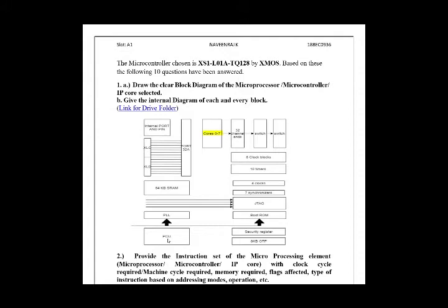Suppose there's some oscillator frequency, and we have some tile frequency. Based on this, the PLL ratio is set, and there are some PLL settings too: OD, F, and R. That's out of scope, but the OD, F, and R values can be modified by writing to a digital node PLL configuration register. There's something called the PLL configuration register, and these values can be changed by writing to these nodes. Okay, so that's all. Now let's talk about the boot ROM.